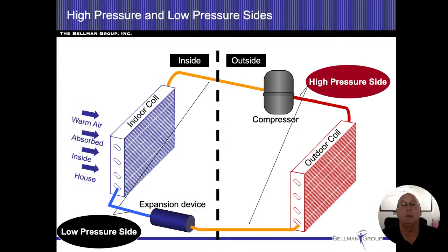And this much right here with this drawing, I am expecting you to be able to write this down or draw this down. I want you to know there's 4 main components of an air conditioning system. All right. We're going to have our indoor coils and our outdoor coils. We're going to have a compressor, so something to increase the pressure, and then something, whether it's the capillary tubes or TXV, for a generic term, we're going to call it an expansion device, all right? So we're going to have something that's going to lower the pressure, or a metering device. I like that as more of a generic term as well.